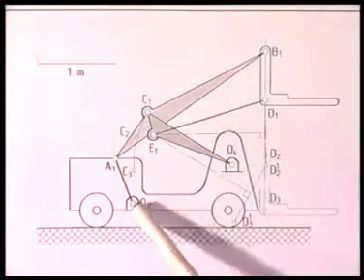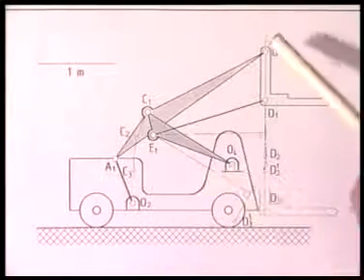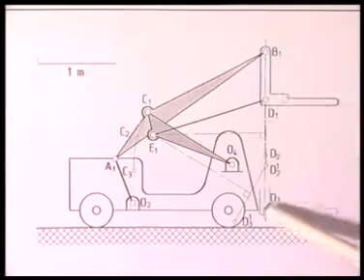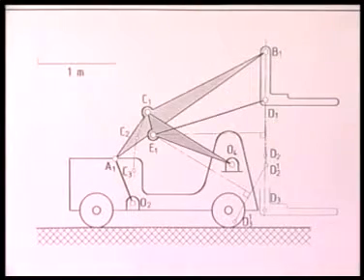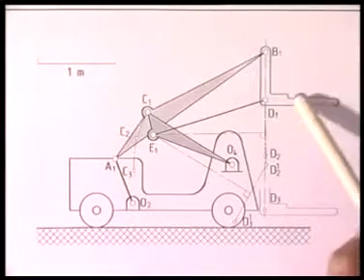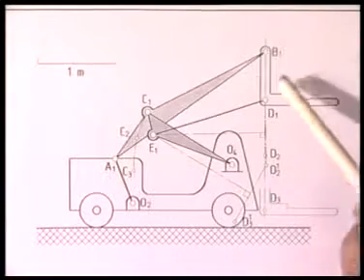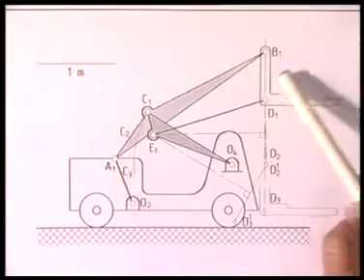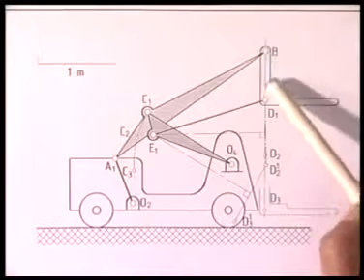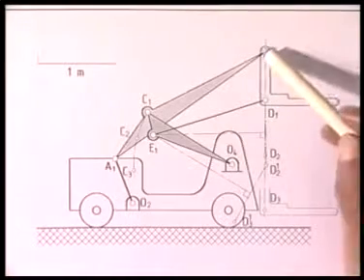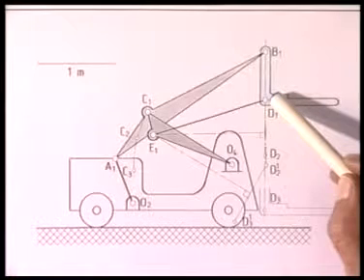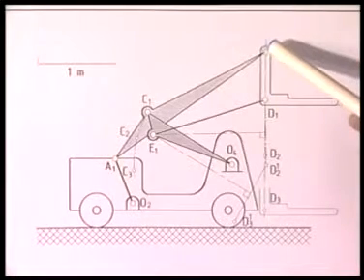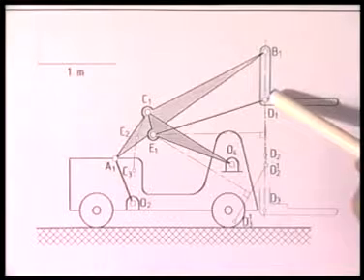We had already chosen O2, O4 and this vertical line on which I had B1, B2 and B3. But if this fork is hinged at only one point, this will be swinging like a pendulum. So to guide this fork vertically, I choose another convenient point D1. This is chosen arbitrarily.